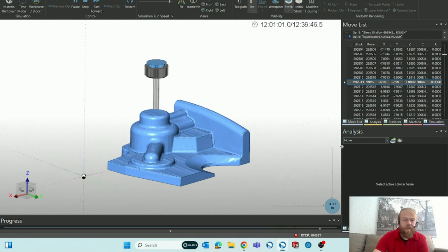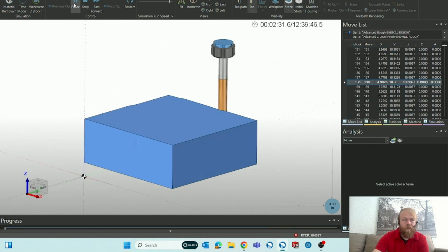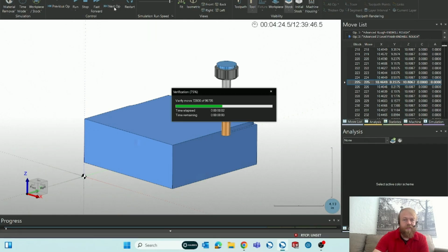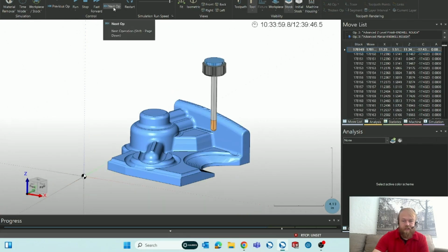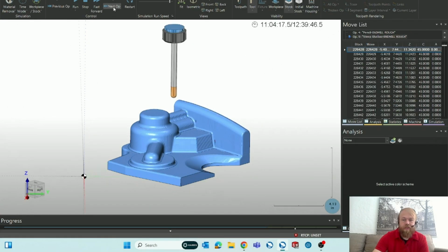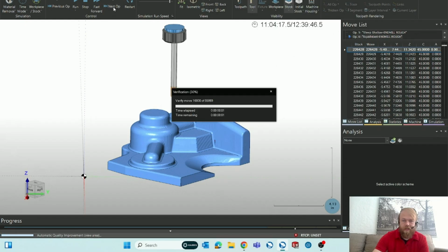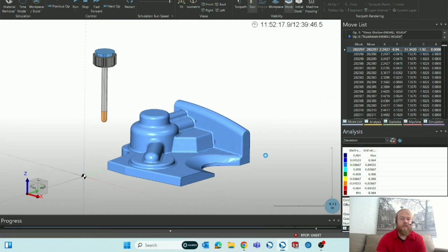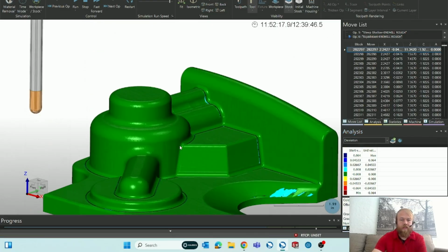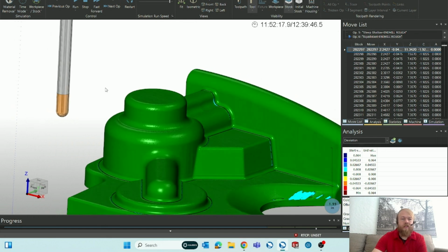So we looked at not only tilting the tool in 5-axis, but once everything is finished up here, we can, oops, I just hit restart. Not only do we have the 5-axis tilt that we looked at today, we also looked at the simulation and being able to go to the deviation report and load the colors in depending on how much material is remaining. So we can see that everything is cut to size by tilting the tool and using that tool to be able to fit into the corners better and not have any gouging on the side walls and things like that.